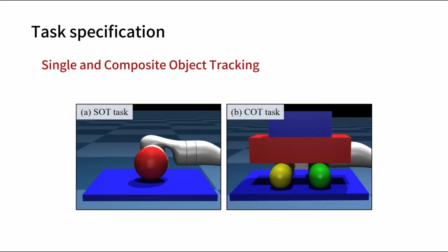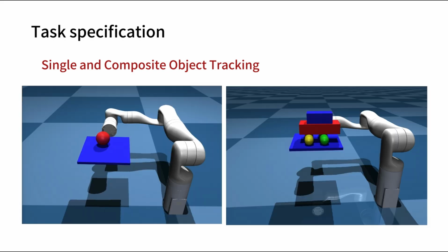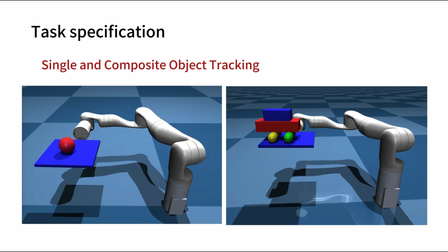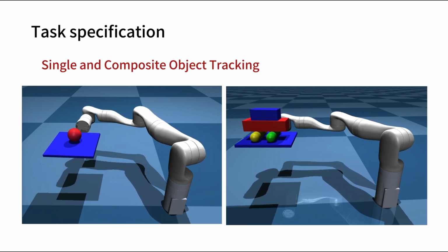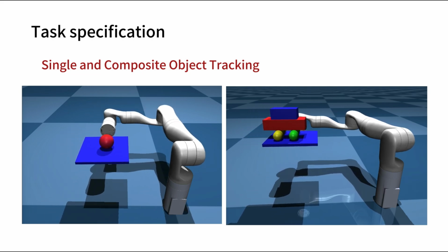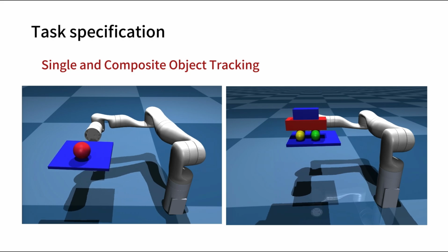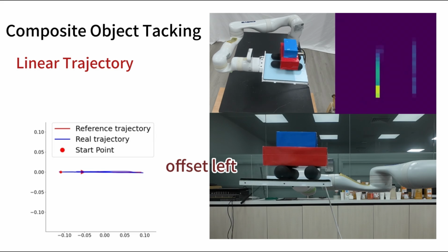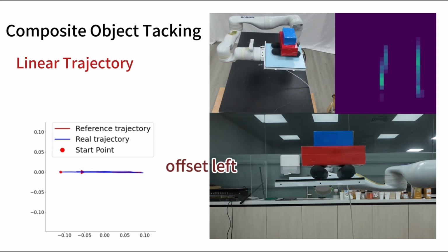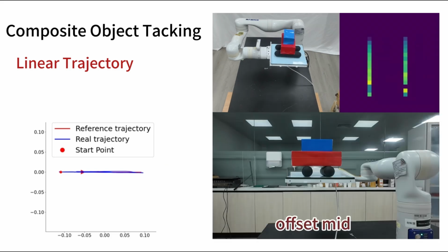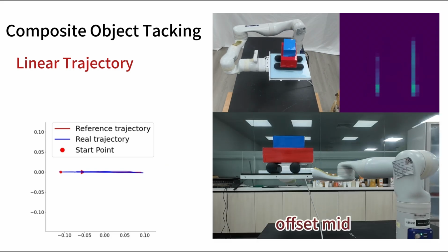We demonstrate our method on two tactile-only tasks, single and composite object tracking, SOT and COT. The goal is to balance an object on a tray while tracking a dynamic trajectory. The COT task is more complex, requiring the robot to maintain the structural integrity of a multi-part toy car. We train our policies to track 4 different trajectories and achieve zero-shot transfer to the real world. In the COT task, we shift the car's body forward/backward relative to its wheels at initialization.